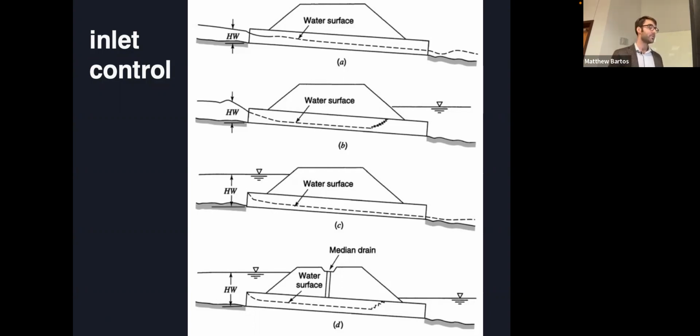in the real world. So in the first example, A, neither end of the culvert is submerged, but critical depth is achieved just downstream of the entrance, and it's supercritical throughout most of the barrel, with the flow approaching the normal depth at the outlet. Okay, so if you have a long culvert in particular, generally you will approach the normal depth at the outlet. Okay. So another case is B.